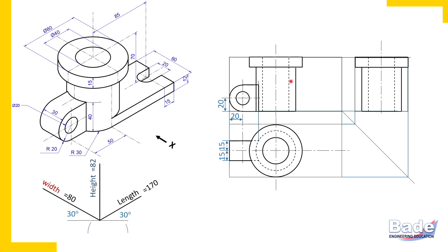This cylindrical surface has a boundary generator which we have made dark in the front view. But check here, this curved surface, the cylindrical surface, is only above the U-shaped block, not below that. This end generator or boundary generator is the boundary of the curved surface, and the curved surface is only above the block.